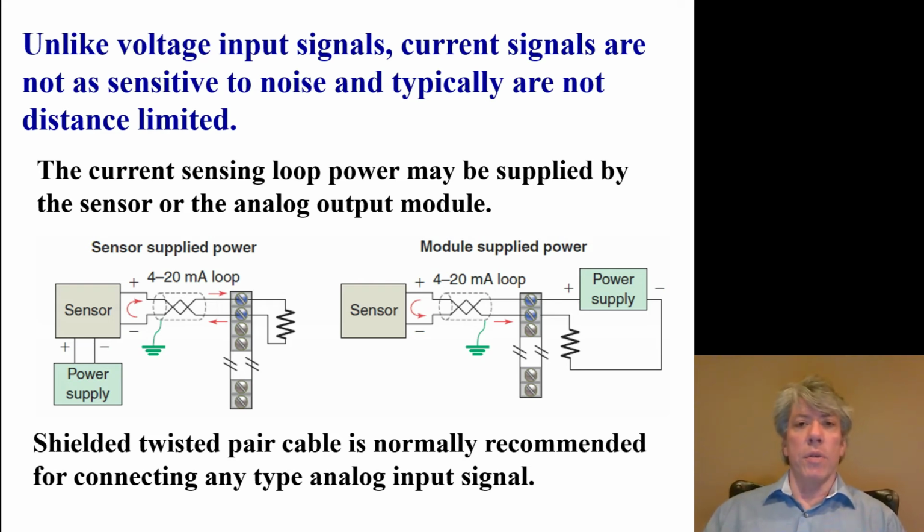Well, you have to use some type of electrical signal. The problem with voltage signals, if you have, say, a 0 to 10 volt signal coming out of your sensor, is that it has to be connected back to the PLC by wire, and copper wire is most common. But even copper wire, though it's a good conductor, has resistance, and so that voltage signal will actually decrease. Say your sensor's out a mile away from your PLC. If you've got a mile of copper wire and only a 10 volt signal, I guarantee you the voltage is going to drop by the time it gets back to the PLC.